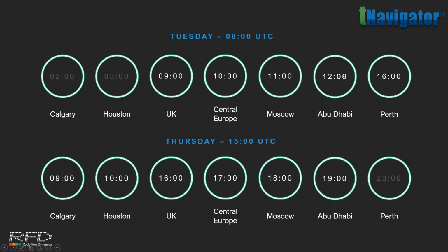Let me take another question. Can this tool be used when you want to complete in 2 different formations? Yes, perfectly. In the demo, I showed a fixed depth to water-oil contact, but you can also set horizons. So first, you need to get the horizon for your formations, the top and the bottom.